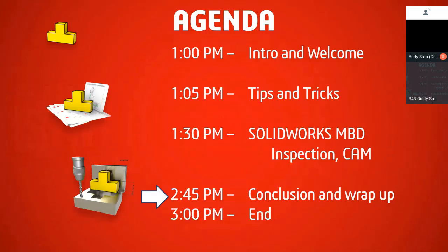You have notes on there as part of the product manufacturing information. We do that in SolidWorks because it allows us to avoid the process of dimensioning every single edge on the drawing the way we would traditionally do it, and instead hand off the model to the machinist with specific dimensions that need to be held to a tighter tolerance, and then a general tolerance for all the other geometry. And not only can it be used by the machining team, but it can also be used by the inspection team in that same kind of downstream flow.